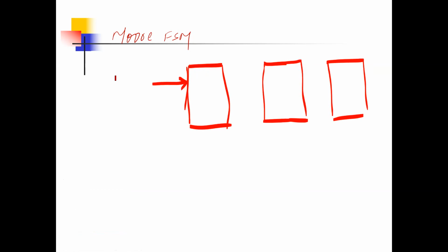Say the input sequence for the machine is W, and the output is small y, which is the next state. This is the combinational logic circuit, which holds the next state logic. And this is the state updation. It is nothing but a flip-flop, a sequential element. The last one is the output logic.